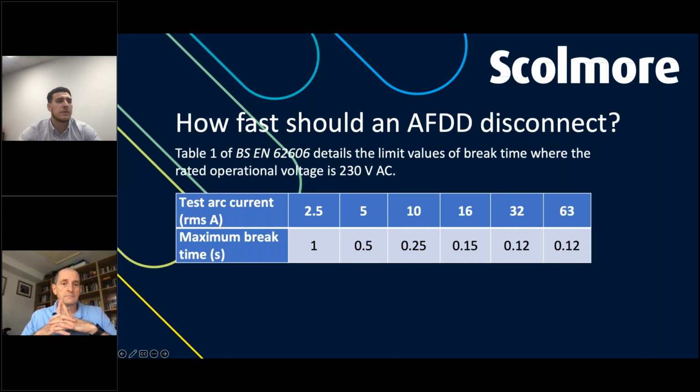So Tim, when we think about a shower circuit, are we suggesting that there's probably too much energy and it's going to operate too quickly? I suppose the issue is once you get to values exceeding the 30 amps or so, you've almost got to the point where, shall we say, the fire's already happening. It's happening so rapidly because you're dealing with so much current in a series arc that the struggle to measure it has already happened before it's thought of saying, is this a dodgy arc?